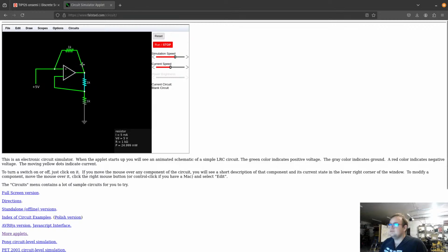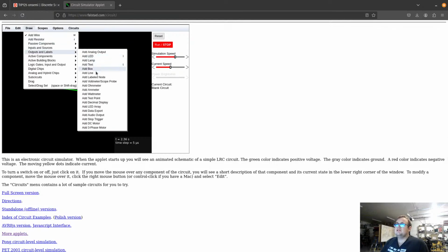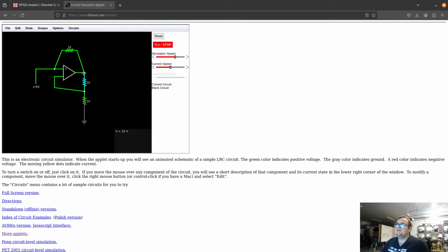So we'll just use, it doesn't actually give us a non-inverted amplifier, figure 2.5. Let's go to 2.5. Now we'll just keep these as they are here. So here we'll also draw in outputs and labels. Test point, we'll say. Okay, so there's our test point.